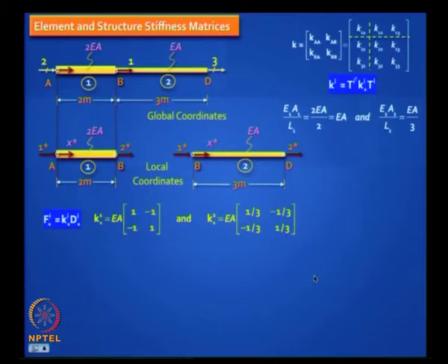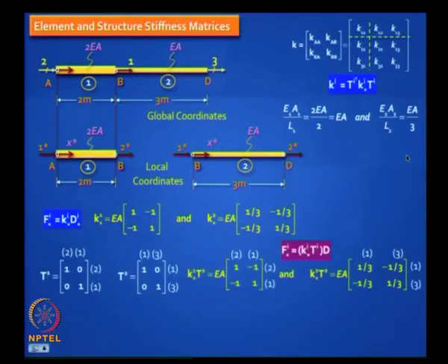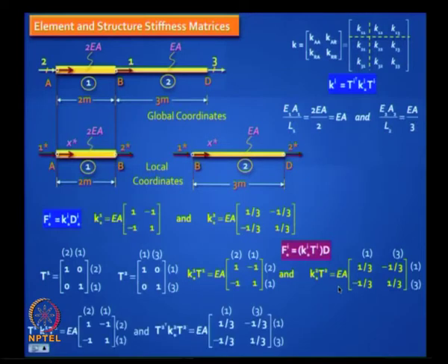Then you do the transformation, you have T1 T2. You need to do this, but it is better to do this first, because you will need this to get the internal forces. This is actually very easy because you are multiplying with an identity matrix, but now you are putting the linking coordinates, and again you multiply with T1 transpose, you will get that. So finally you have got these values.